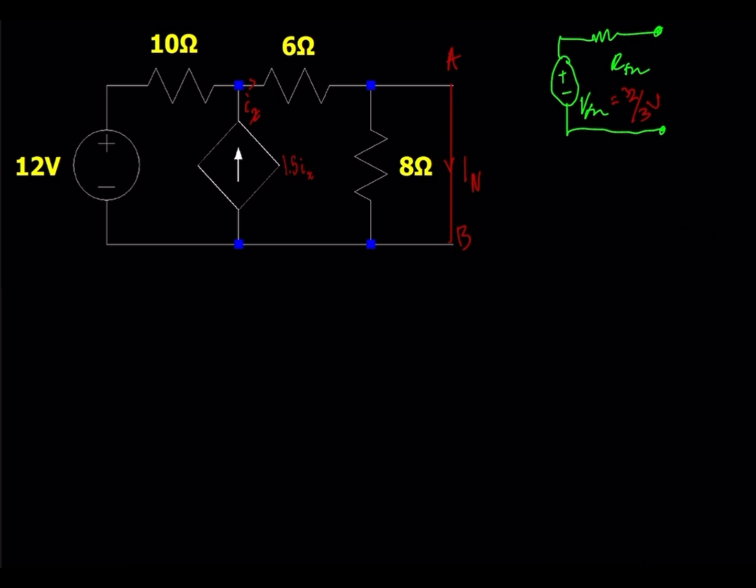So we just need to solve this circuit and find out what this current actually is. I'm going to use node voltage method here just because we have a lot of current variables defined here, and node voltage method lends itself well to that because we're writing KCL equations. So the first step here is to identify our nodes and find our reference node that we're gonna label.